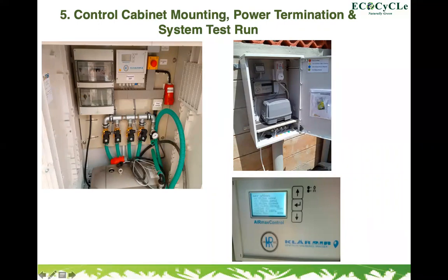The most important component that controls everything is the PLC on the far right down. The PLC is a computer. The computer has a program in it that's able to control all the systems. We told you that this system is automated. So once we do the first stage, which is called filling, which is taking the sewage from the second tank to the treatment tank, that's signaled by the computer. The aeration, this application of air, is also signaled by the computer. The clear water discharge and all those processes are signaled by the computer.